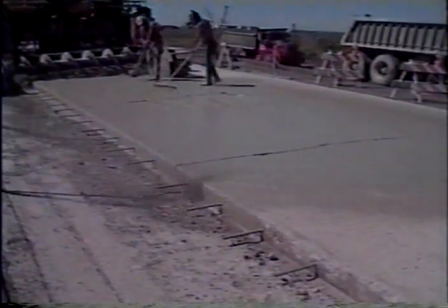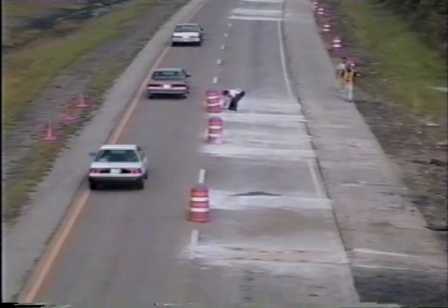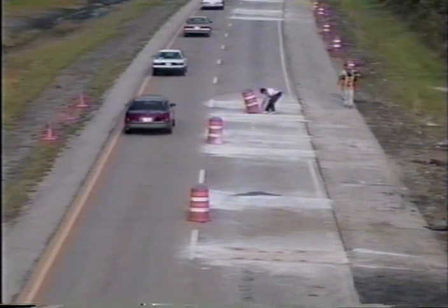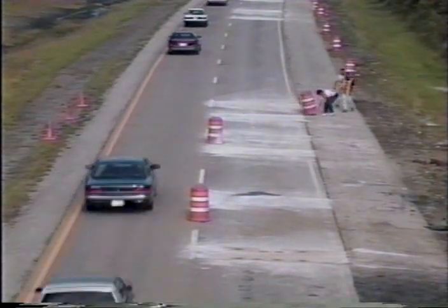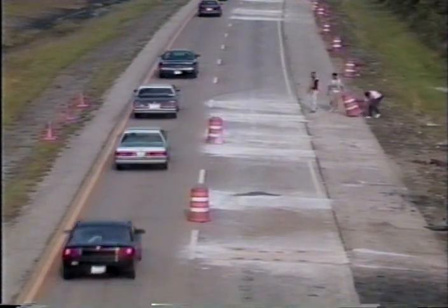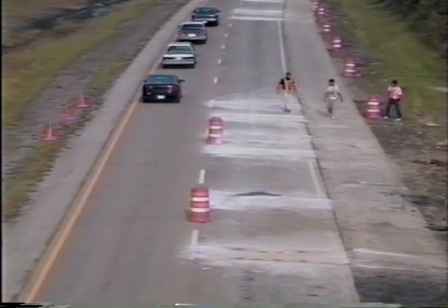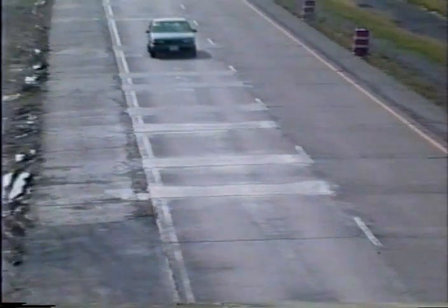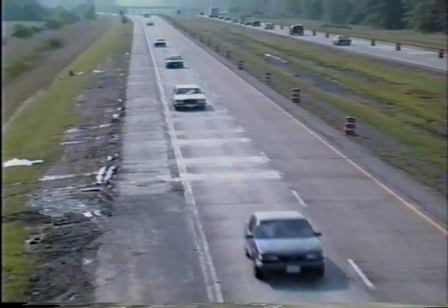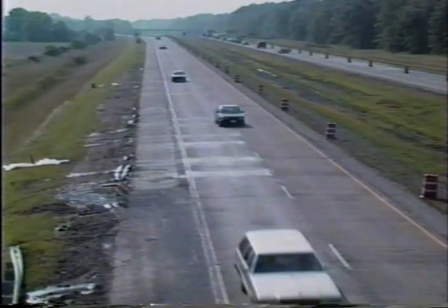As was stated earlier, many recent developments in materials and processes allow for concrete repairs and new pavements to be open to traffic at a very early age. For example, full depth repairs can be constructed to reach a flexural strength exceeding 300 psi in as little as 4 hours, permitting them to be open to traffic that soon.